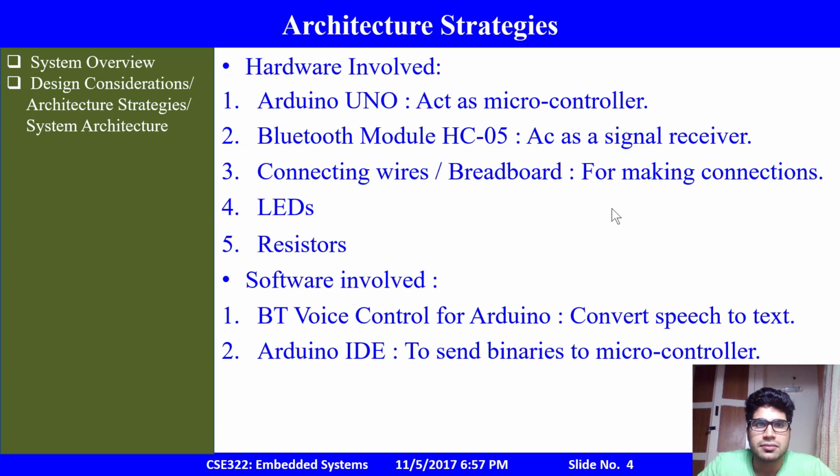While talking about the system architecture, the hardware involved is the Arduino Uno, which acts as our microcontroller, and a Bluetooth module, the HC05, which acts as a receiver for our microcontroller, and wire breadboards used for making connections, and the LED and resistors which are used to replace the electronic appliances we are going to control with our system.